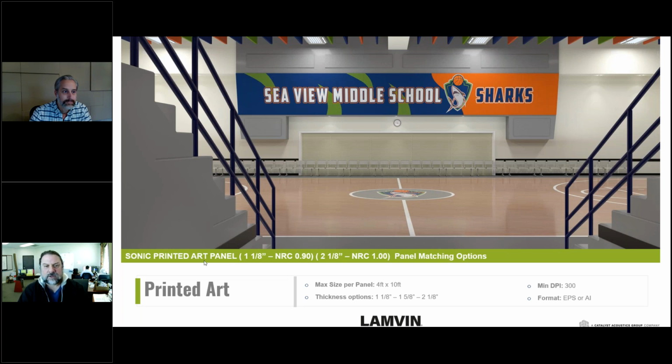I also want to point out the face, right there. Usually in these multi-purpose rooms or gyms, it's a copolymer facing for the super high impact. Good point. So typically it's 2-inch with a copolymer face, or 1-inch tackable. But more to the point, we would lay these out on the floors and ensure that the pattern matching of the digital images, one to the next, is spot on, with minimal seam in between them.